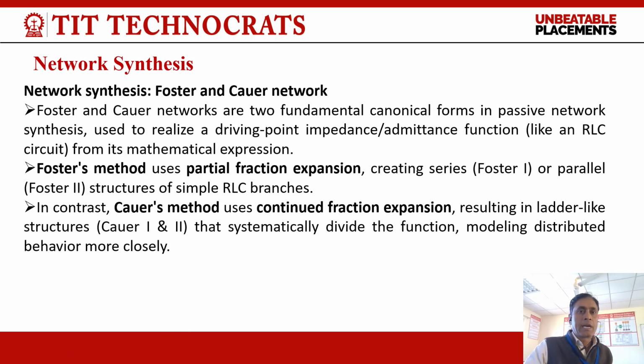Next, network synthesis: Foster and Cauer network. Foster and Cauer networks are fundamental canonical forms of passive network synthesis used to realize a driving point impedance or admittance function like an RLC circuit from its mathematical expression.